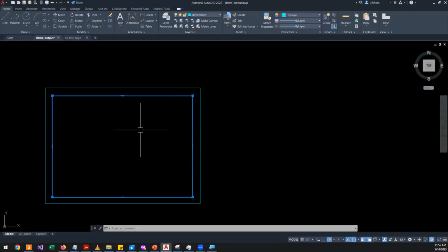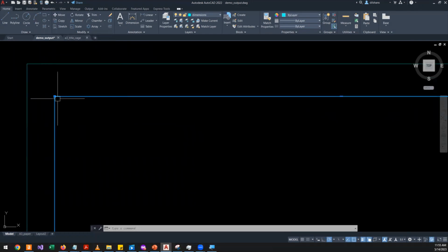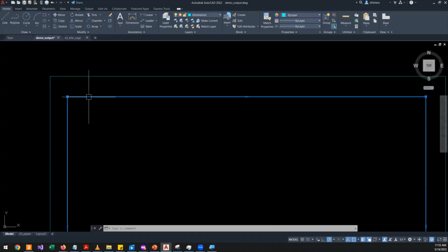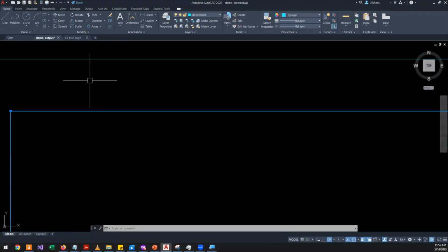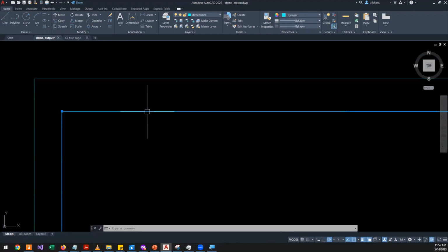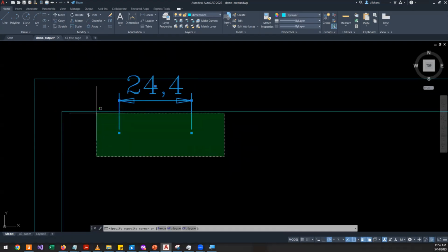So here, you must make sure that your drawing does not exceed the margin. If it goes beyond, then you will not get any output in this region. It will simply be kept blank. Let's say you have an important dimension going beyond the margins, then once you print, you will see only this region. So the numbers will be clipped out.